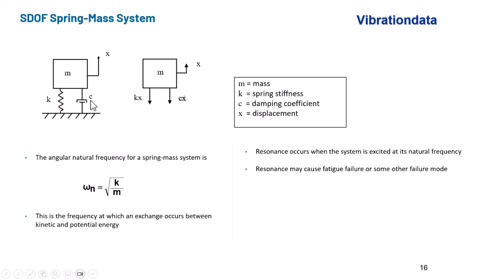Now the damping, there is no Newton's law for damping. There's no free body diagram to help us predict what damping is. Damping can only be measured. But if you have some new component that you have not even built a prototype yet, we can draw upon reference databases for damping, or sometimes we just have to assume a lower and upper bounds for damping as we go along.